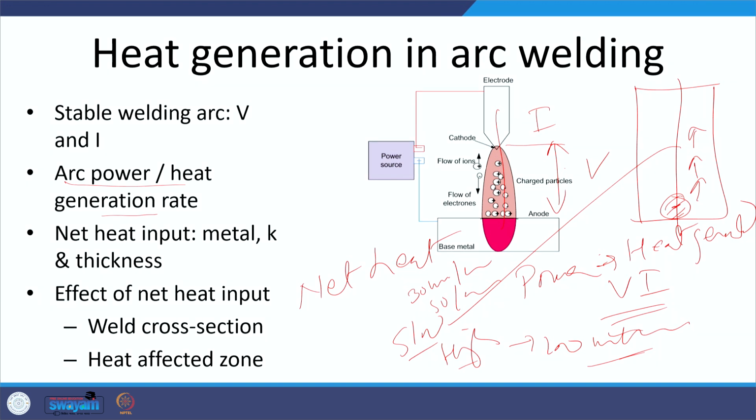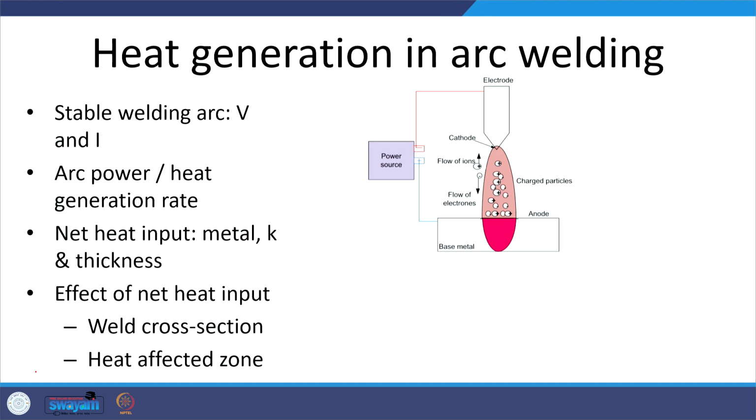So, there can be a lot of variation in the speed at which the arc is moved during the welding. This speed is crucial since our heat is being generated at this rate, but it will not be delivered at that rate because that will depend upon the speed of the arc. So, if we have the welding speed in terms of minutes, then we can simply convert it to welding speed per second, okay, this is one.